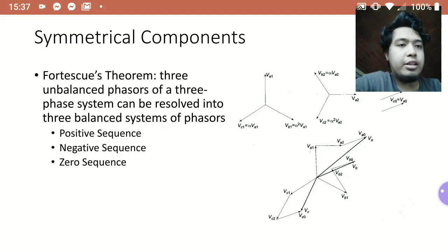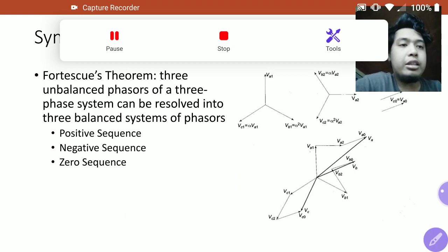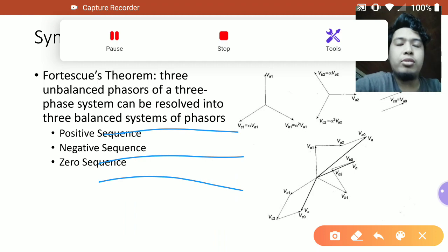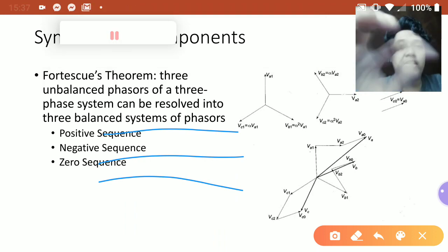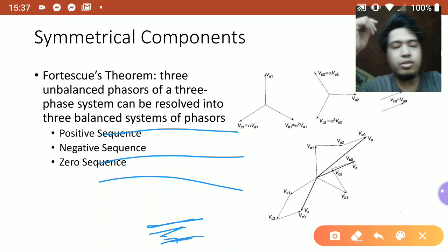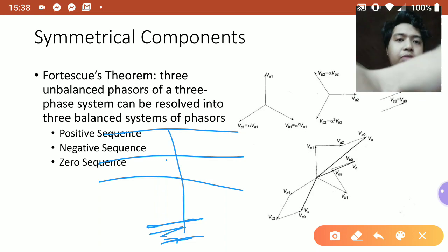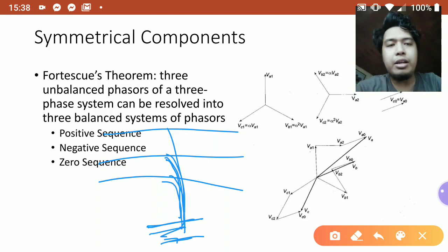Suppose let's say that I have this three line system. So it's a three phase. So those three lines, that's my three phase line. This is my ground. So for this consideration example, I'll just demonstrate shunt fault, grounded shunt fault. Yeah, it's a short circuit fault. So if we consider a three-phase fault, that's basically if all of these three lines are connected to each other. They can be grounded, they can be not grounded. It's basically the same. Okay.